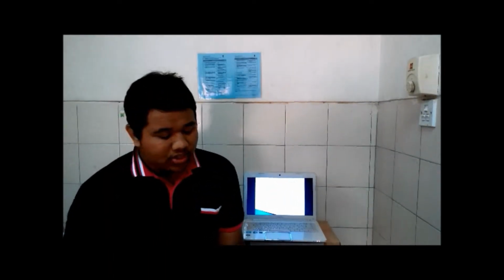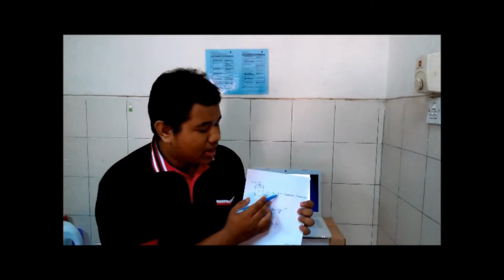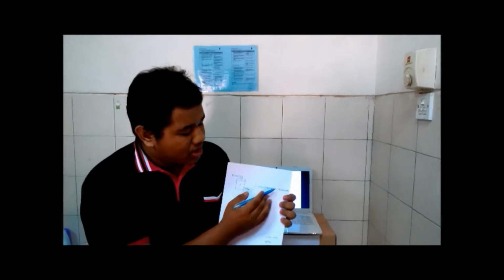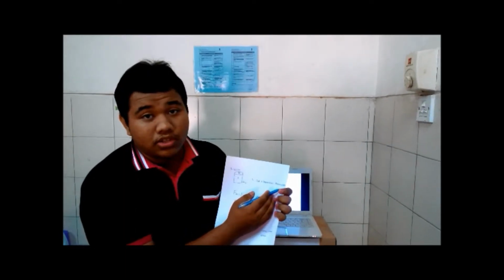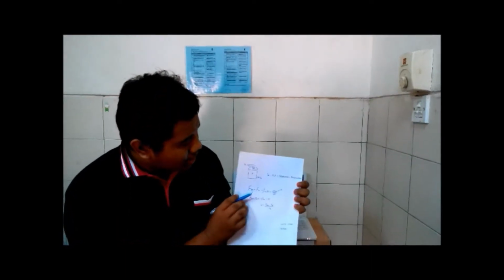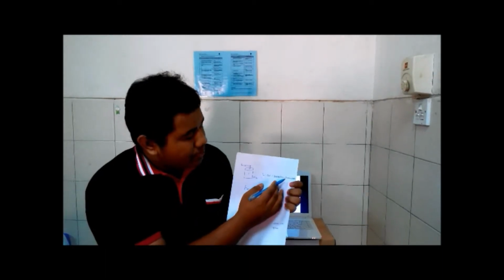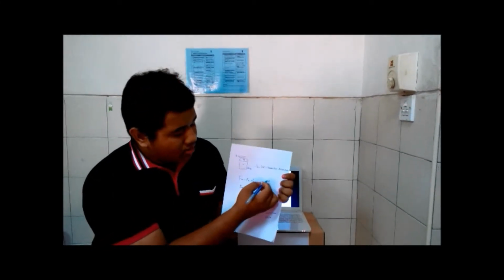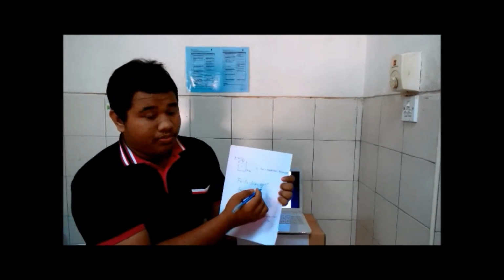The first one is, as we know, in minus out plus generation equal to accumulation. For CSTR, we have no accumulation. Why no accumulation? Because the flow into the tank is equal to the flow out of the tank. So we cancel out the accumulation.